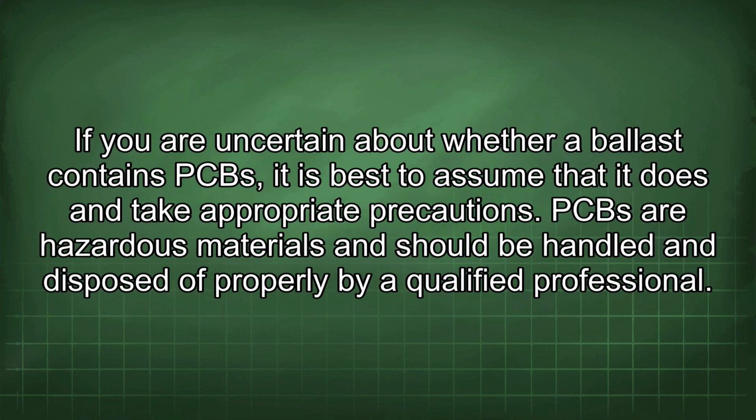If you're uncertain about whether a ballast contains PCB, it is best to assume that it does and take appropriate precautions. PCB are hazardous materials and should be handled and disposed of properly by a qualified professional.